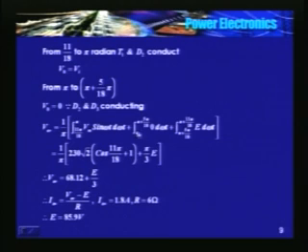From the end of the freewheeling mode till you trigger the next pair, that is pi plus 110 degrees, it is E d omega t. So this is half a cycle. You substitute the value for Vm as 230 into root 2, integrate it. So this is the average value.